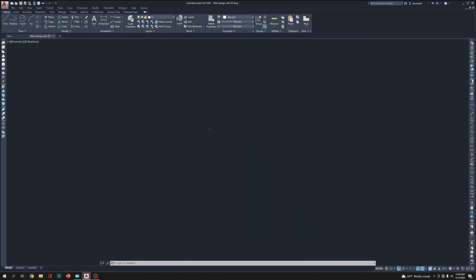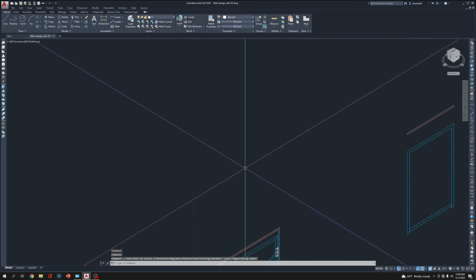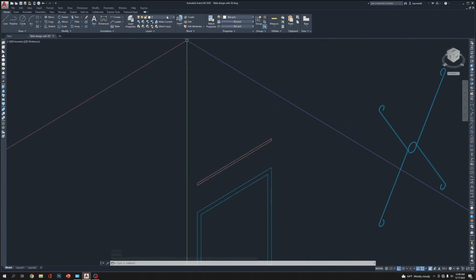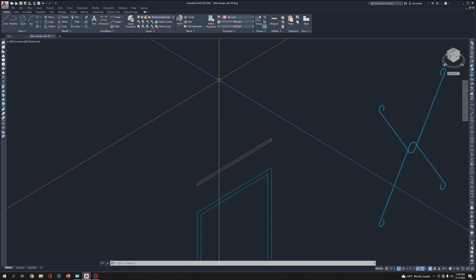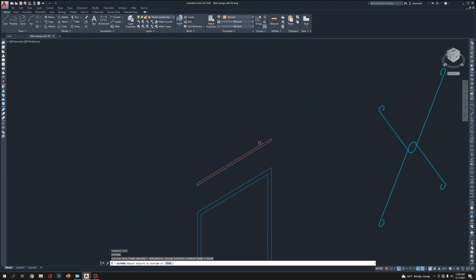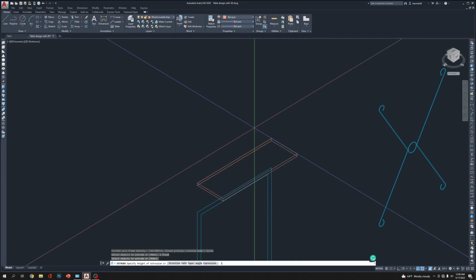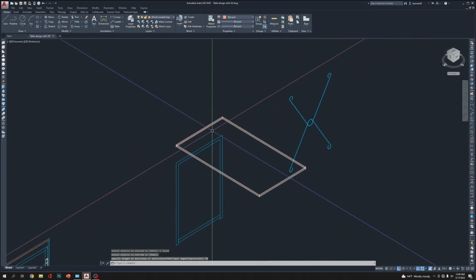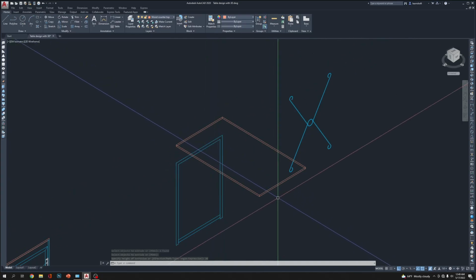So this isometric view is gonna be helpful. Now this one helpful, this one helpful. So let's say this is the tabletop, right? The wood. Go to change the layer, EXT, enter. This one should be 3 feet long, enter. 36, enter. So this becomes 36, but it came this way.